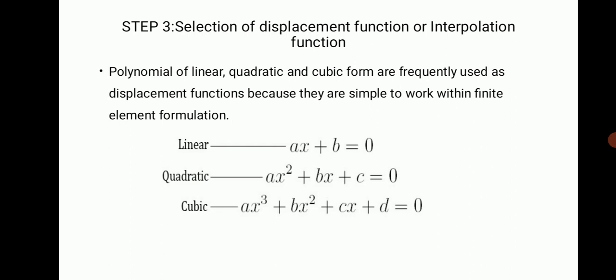And the step 3 is selection of displacement function or interpolation function. It involves choosing a displacement function within each element. Polynomials of linear, quadratic and cubic form are frequently used as displacement functions because they are simple to work with in finite element formulation.